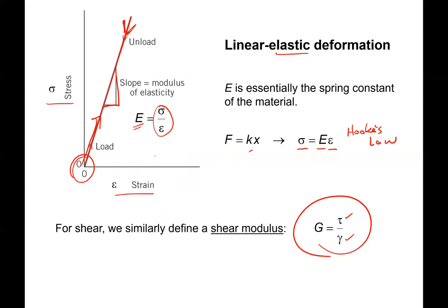We're only stretching bonds. And in many material systems, this initial region of the stress strain curve is also linear. So under those conditions, we can simply take the slope of this linear region and define that as our elastic modulus, or Young's modulus, which is another way of referring to this value. That typically has units of gigapascals for metals, maybe megapascals for polymers.